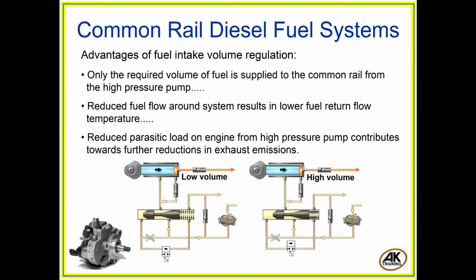Advantages of fuel intake volume regulation. Only the required volume of fuel is supplied to the common rail from the high-pressure pump. Reduced fuel flow around system results in lower fuel return flow temperature. Reduced parasitic load on engine from high-pressure pump contributes towards further reductions in exhaust emissions.